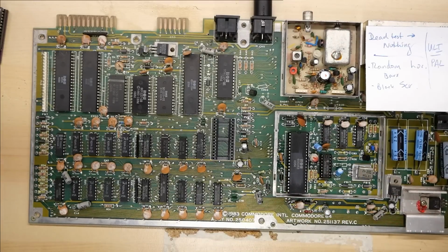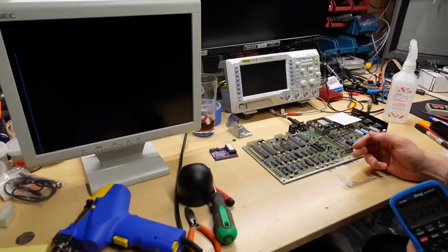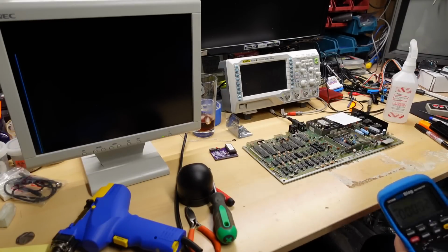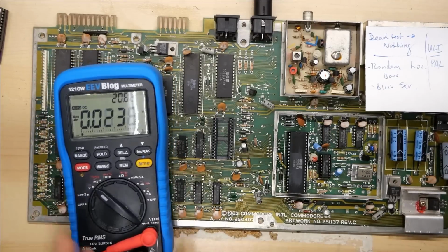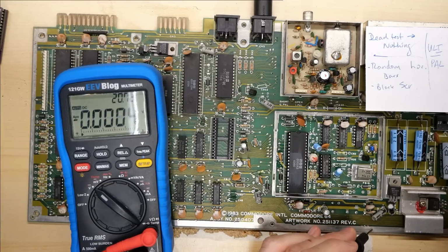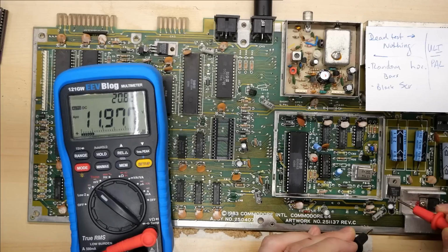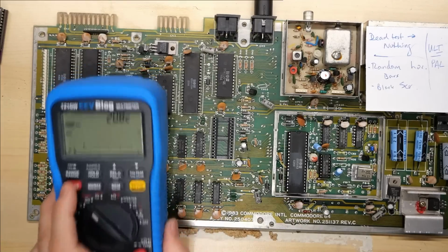All right, let me turn this on. Let's quickly confirm the trouble that I wrote on the note here. Okay, the screen is coming on. Yep, black screen, so not even any bars. All right, so we have the multimeter here. First, let's do some checks just to see if the voltage rails are indeed correct. We have 5.0 volts there, which is perfect, and 11.9 on the 12 volt rail, which is also perfect. So there's no danger to running this machine.